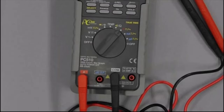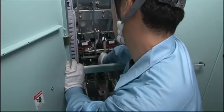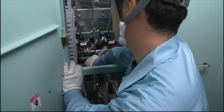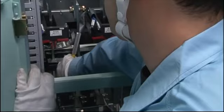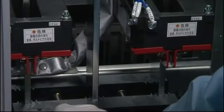For example, when you intend to measure voltage, check whether the probe is inserted into the voltage measurement socket and whether the measurement range setting is correct. If a ratchet touches a terminal while you're working, you may suffer an arc burn on your hands. In some cases, your work clothing may catch fire.